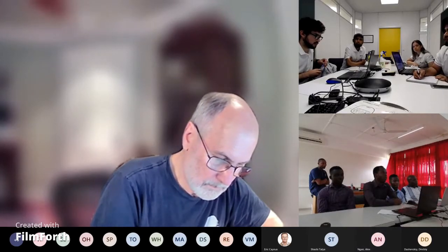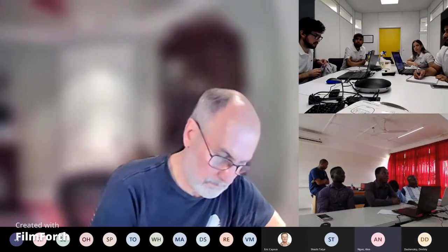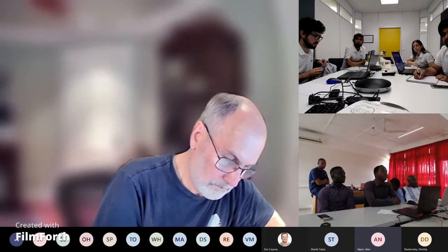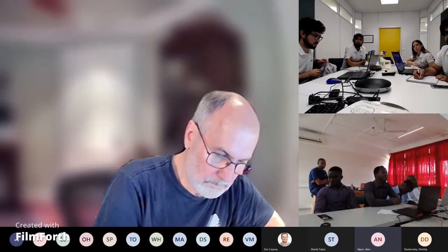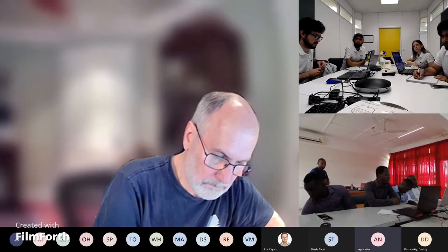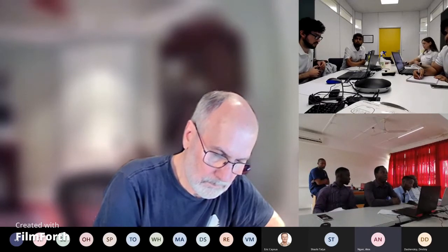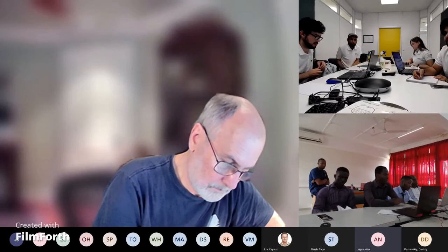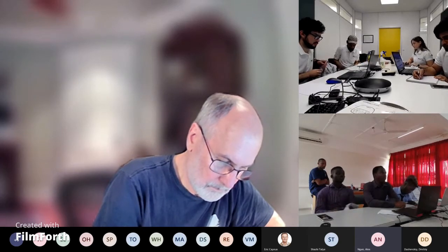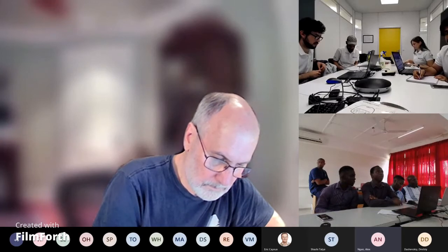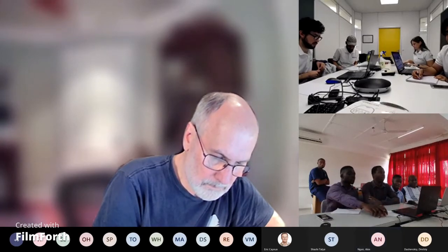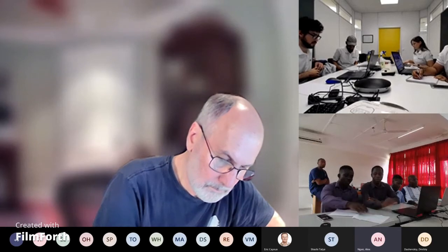I'm assuming only the friction factor in my model. The friction factor has minimal impact. The more important thing is there will be a significant change in your ROP due to the hardness of the formation. Basically, the unconfined stress, or the compressive strength of the formation. So when you talk about stick slip, this is something you definitely need to consider if you want to replicate the real world. Okay, yeah, I got it.